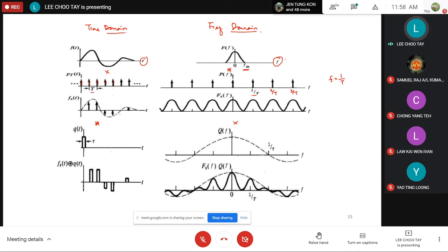The amplitude of your spectrum now, centered at 0 frequency, is the highest because of this sinc envelope. And then your second spectrum here, the height will actually reduce because the height here is less. Another set here, again at the sampling frequency. So again you're going to have multiple replicas of the baseband spectrum. The shape and the amplitude actually follow the sinc function.